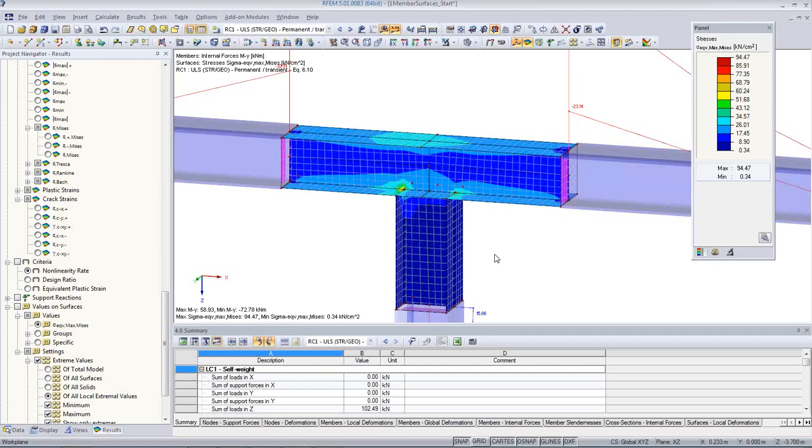Because we can only reduce the stiffness of the entire finite element, we should not evaluate the result separately in each node of the finite element. We should see it as an average over the finite element, as a constant. So, okay, what do I do?